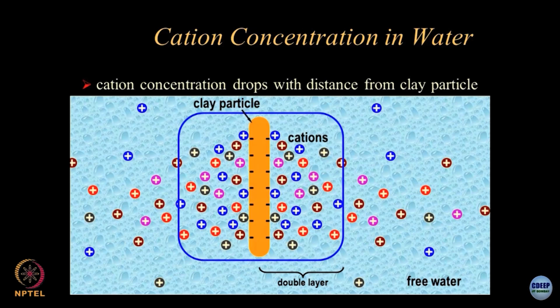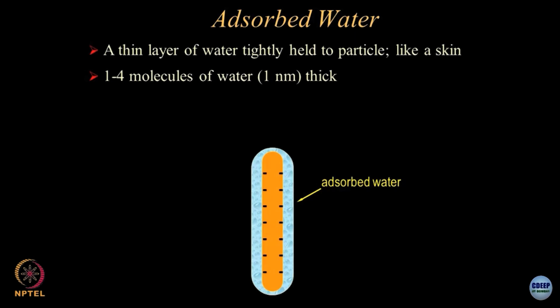Beyond this boundary is all free water. So, adsorbed water is the one which is surrounding the particle of the clay, and this adsorption is because of the water being a dipole, clear. So, you imagine as if on the clay particles you have different dipoles coming together and the positive and negative getting connected with each other, and this is how the adsorbed water gets formed.